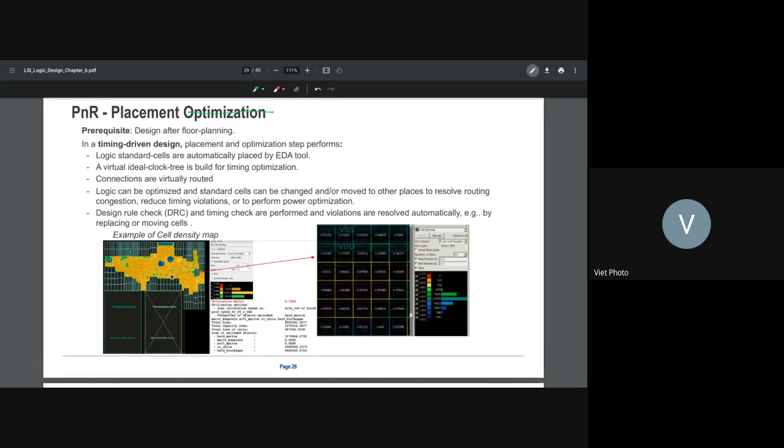They have a criteria. First of all, the target is the frequency. But how do they know the timing? Remember, we need to have some referee to know that this path passes. So we need to have some anchor to compare with the timing of the path, which is the clock, right? Because in the placement we don't have the clock yet, so we have to assume that, right?